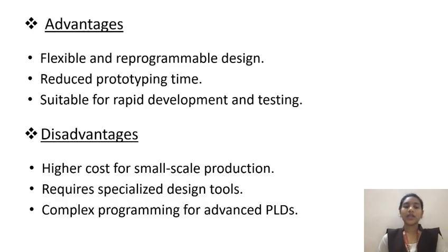So, the advantages and disadvantages of PLDs. The advantages are that they are flexible, they have reprogrammable designs, and they reduce prototyping time, being suitable for rapid development and testing. Some PLDs are also low cost and cheap, and they are very useful. Their disadvantages are that some of them have high cost for small scale production, and they require special design tools, which are costlier and more difficult to get, and complex programming for advanced PLDs.